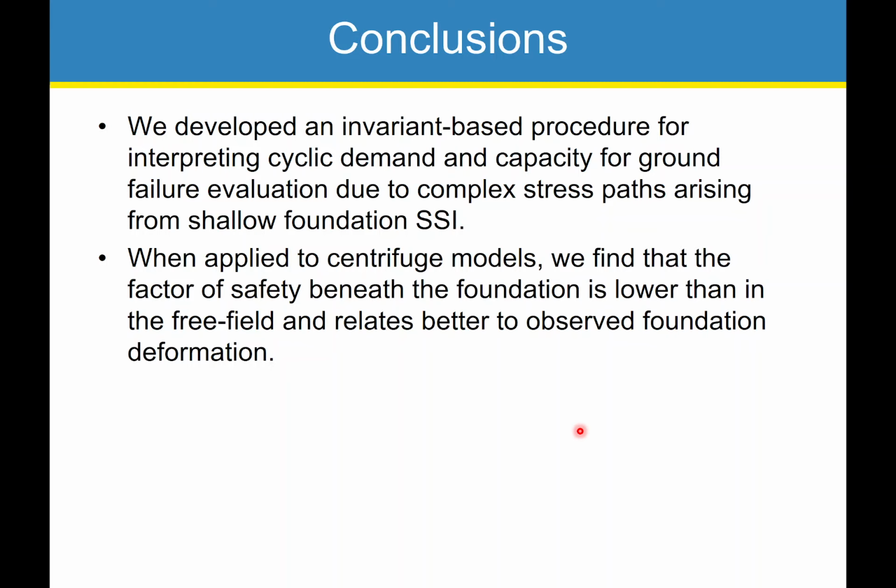In our case, we did this for plane strain conditions. Our centrifuge models were essentially plane strain. The method itself is fully extensible, so you could extend it to 3-dimensional loading conditions. When we applied this to centrifuge models, we find that the factor of safety averaged vertically beneath the corner of the footing was lower than in the free field, and it related better to observed foundation deformation. We would underpredict foundation settlement if we used a free field analysis in this case, which is the traditional method that we do in engineering practice.